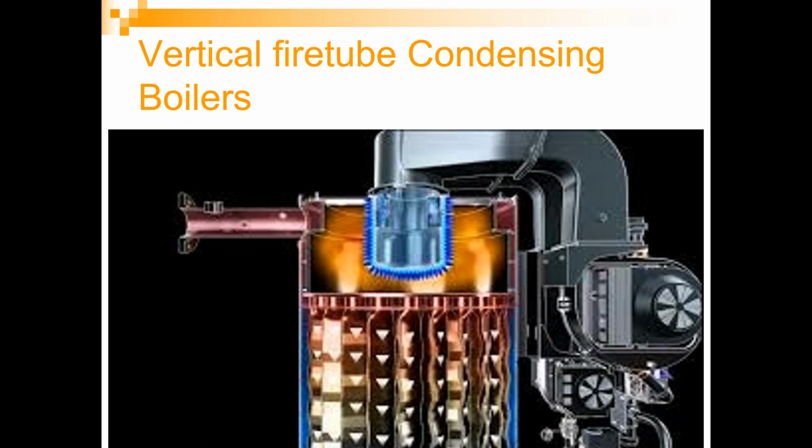And one of the downsides with a Firetube boiler in a hydronic system is the water moves very slowly through the Firetube boiler. Now, why is that an issue? When the water goes from a 4-inch pipe running at 8 to 10 feet per second into a 32-inch diameter pressure vessel, that water is now running at half a foot per second or less. Well, any air bubbles or any dirt that was in the water now comes out of solution. And if you get any air bubbles below the surface of this crown sheet and you have a burner at the top firing down against that tube sheet, those air bubbles act as a layer of insulation. Well, when there's a layer of insulation below that tube sheet and fire on the other side up here, and the water is not taking away that energy, this top tube sheet will deform and crack.